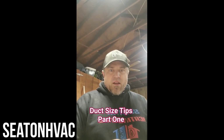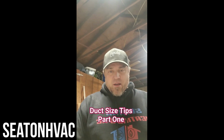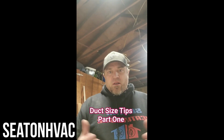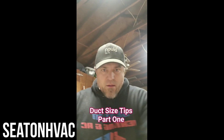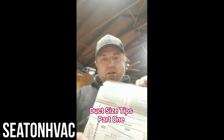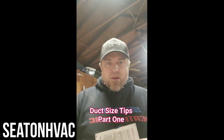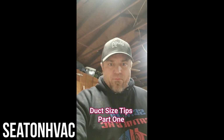Hey guys, Seton HVAC here. So now that we finished up our series on how to do a heat loss on paper, not with a computer program, we're going to start with how you, on your slide rule, on your ductulator here, determine your friction rate. Let me show you the first step.